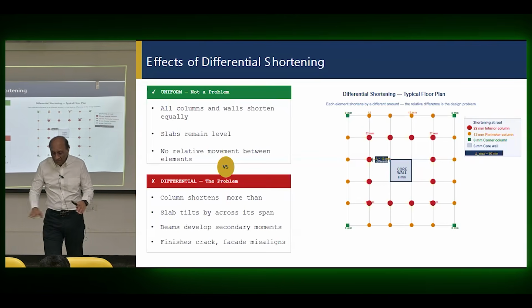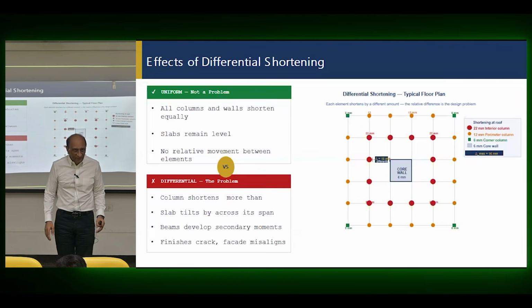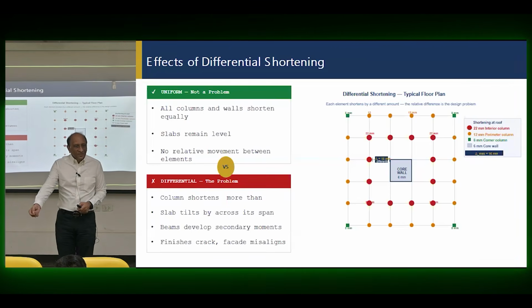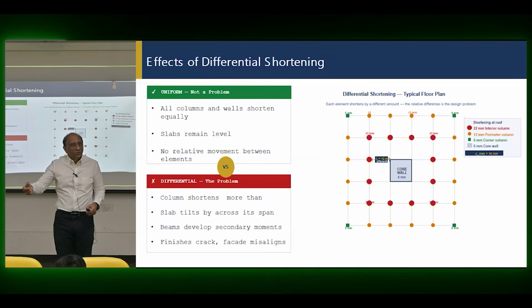They should not make it flat. Their tendency will be, if you don't give them this information, they will just make it flat because that's the default construction. But you have to tell them, no. Don't make it flat. Make this column 5 millimeter above, this column 3 millimeter below, and so on, so that after some time, it will be flat.